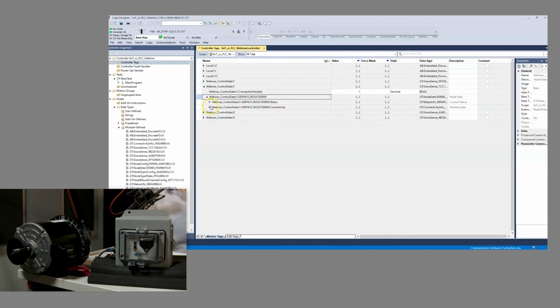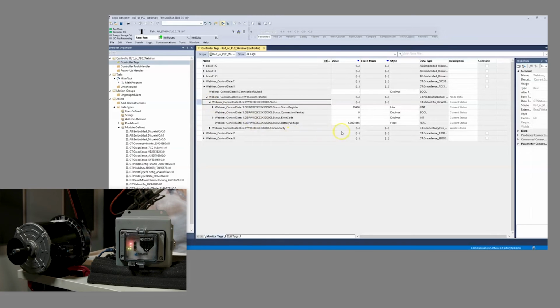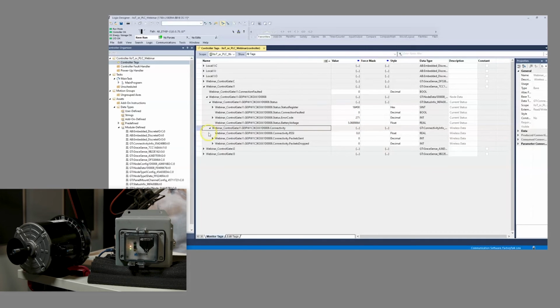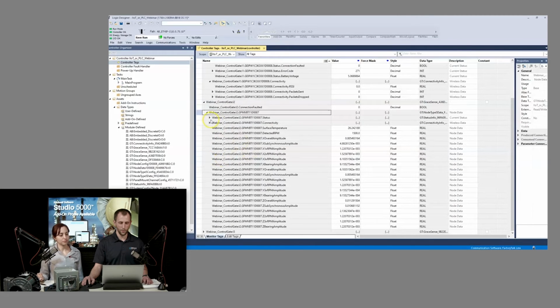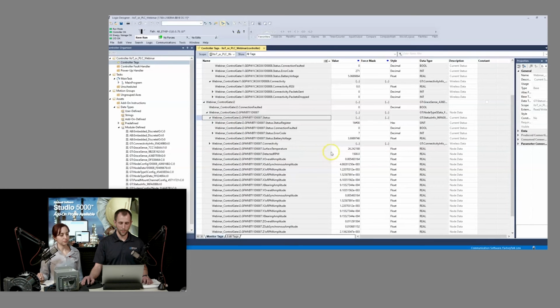We'll go to status. So we'll see we have our first, there's a 24 volt that we're supplying to this, but it is then stepped down to 5 volts inside. So we're looking at that regulated voltage. And then if we go in and we'll look at here's our VBT. So we'll see if we have any data from that yet, and we do. So perfect. So we can see, okay, we have 3.69 volts, which is very good for this battery cell.